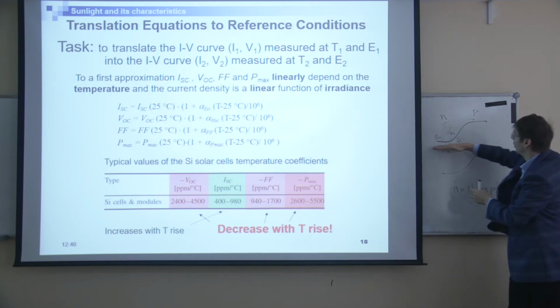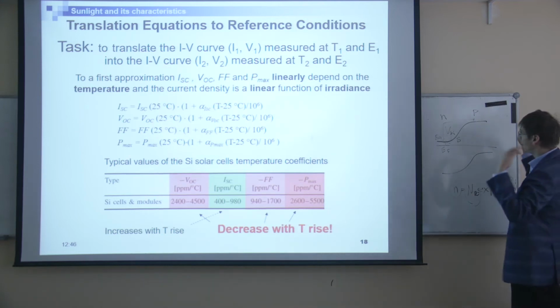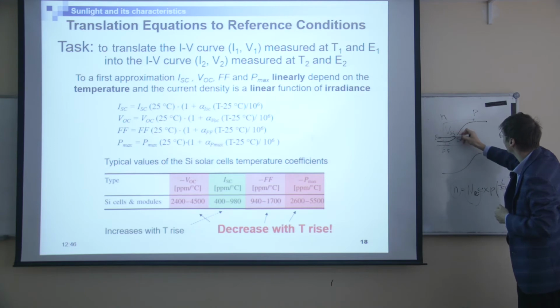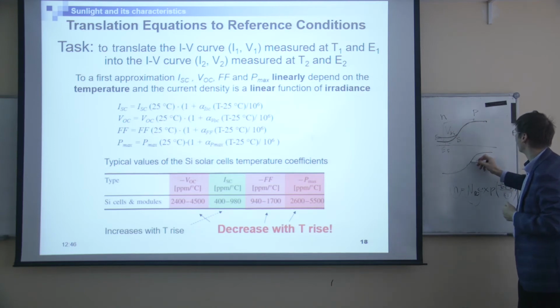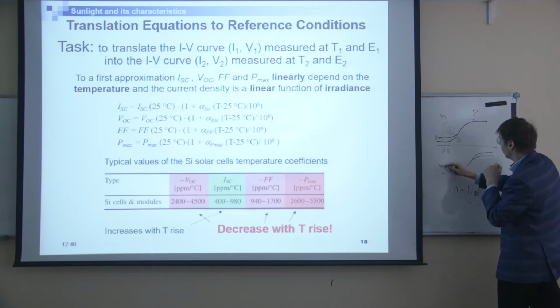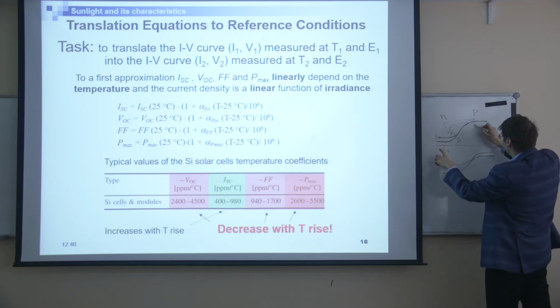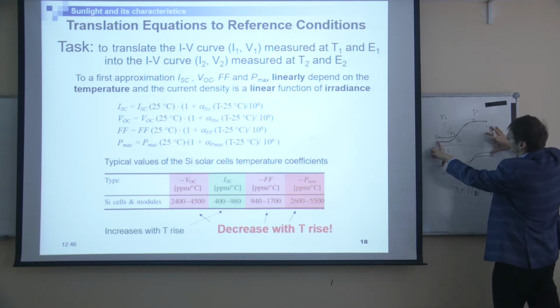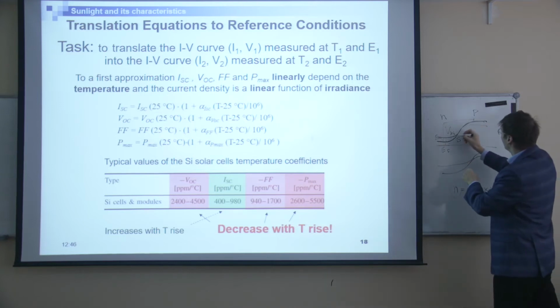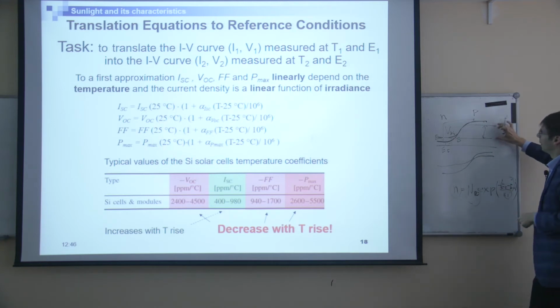But you see the Fermi level should be the same for the p-n junction in equilibrium. So it means that for the higher temperature, you have these changes. So if I fix this at this value, it's like this. And here also there is some shift. So it means for this band gap at higher temperature, we have a small built-in voltage.